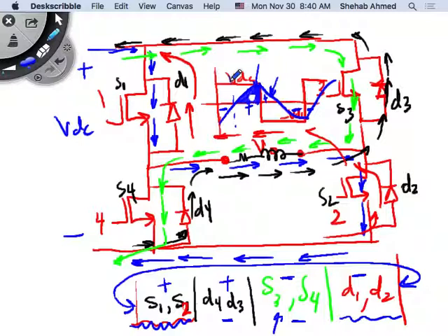Now that you mentioned a larger inductor, the current ripple will reduce, right? Or will something else change as well? No, but here the inductor is actually your load. In the case of multiple switchings per cycle, yes, it's the current ripple that will change for sure.